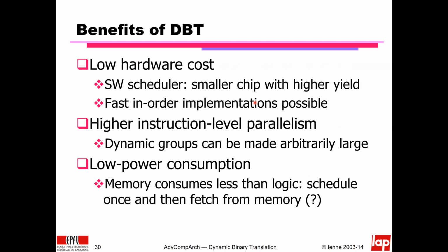There have been a number of advantages. One of the advantages that Transmeta was putting forward, and I never understood exactly the argument, tends to be low power consumption, right? Somehow there is this sense that being a VLIW, it will be more efficient because it doesn't spend time in the scheduling. Of course, it spends time doing millions more instructions for the scheduling in software, but maybe it does it sufficiently rarely that it compensates.